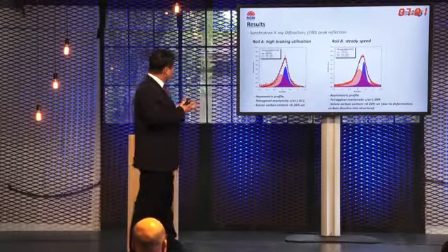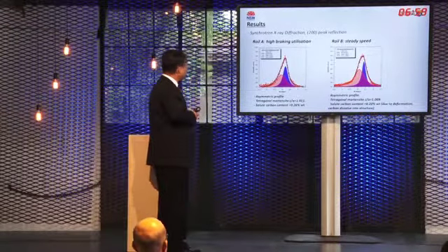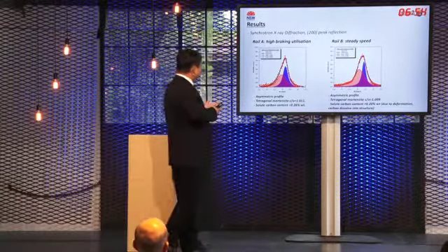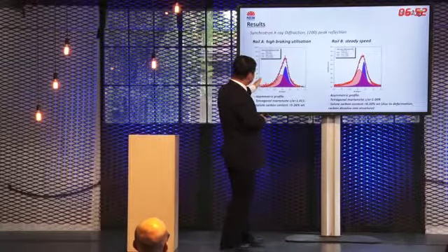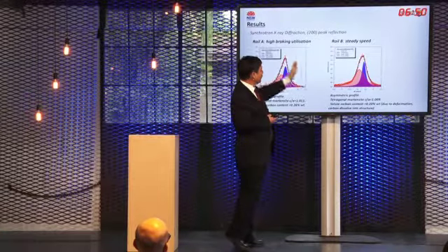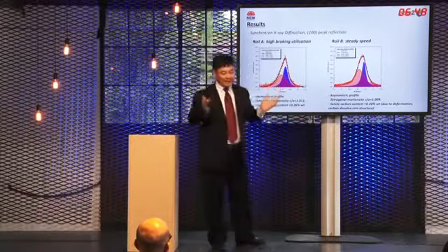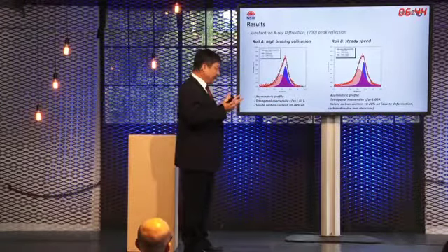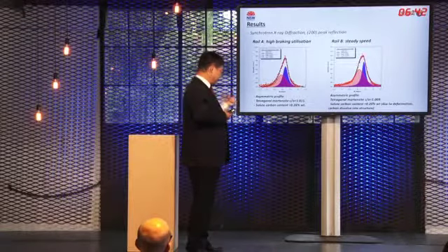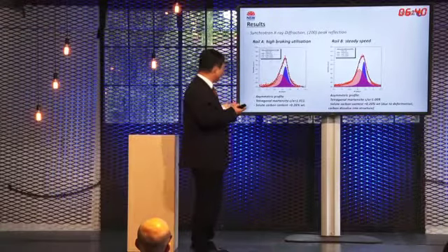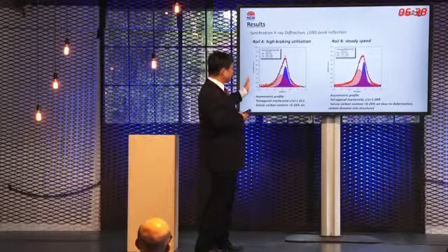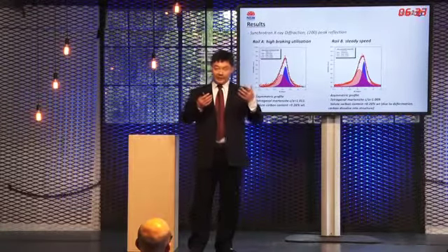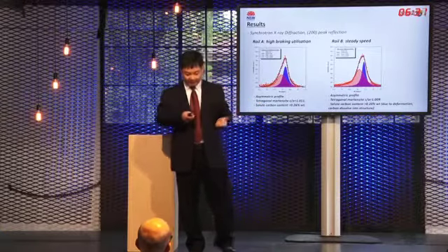We try to do more detailed analysis. We focus on the 200 peak. You see these two peaks, for region A and for region B, are both asymmetrical. Asymmetrical means they are split into 002 and 200, which means it's martensite transformation. So we are sure this white etching layer is a martensite white etching layer.